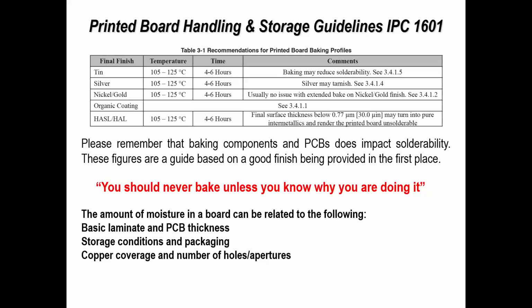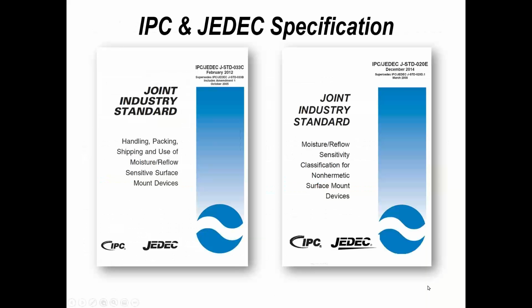But it becomes folklore. So everybody bakes boards, and it may or may not be necessary. So that's all I'm saying. Please think about whether you need to do it or not, but certainly why you're doing it in the first place. If it's something passed down, if you're a brand new engineer hitting the shop floor, you might get told, oh, we always bake that board. But why? Ask the question.